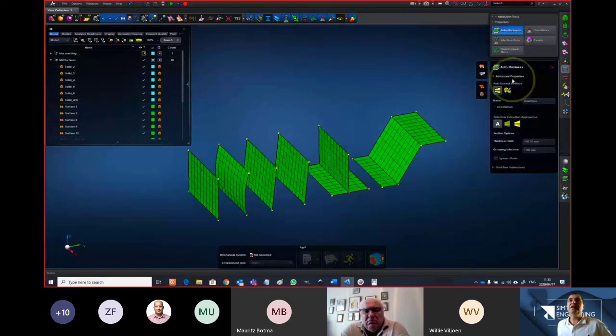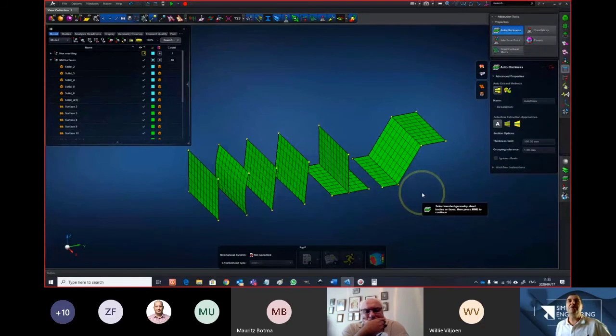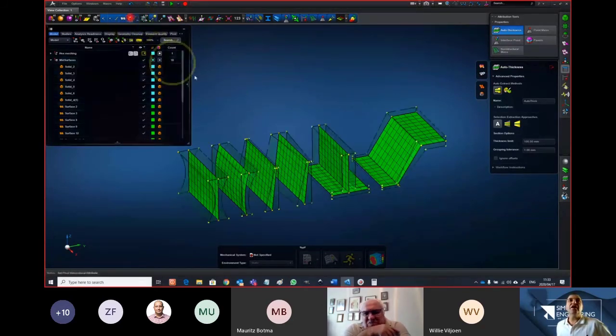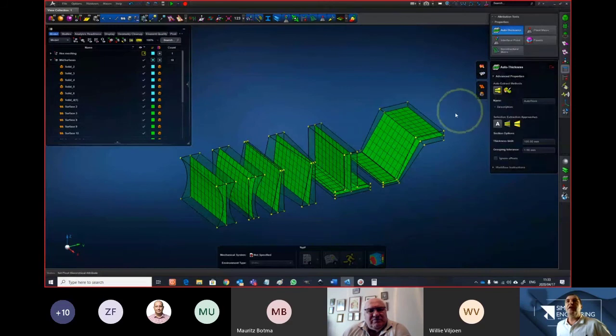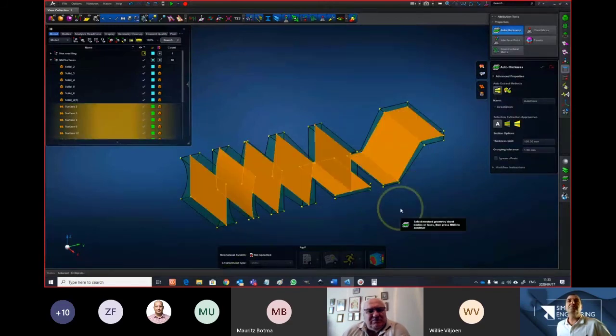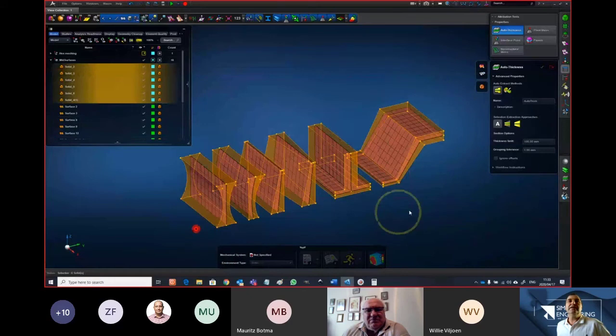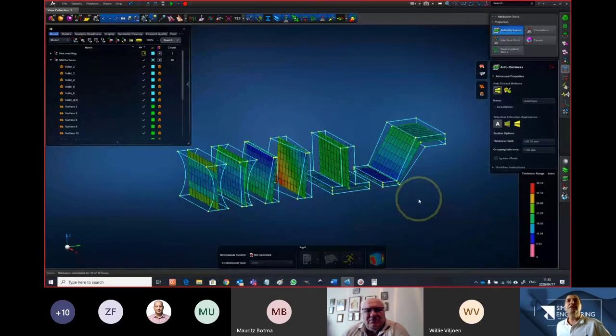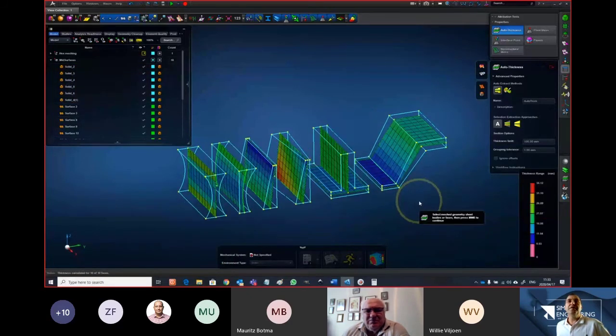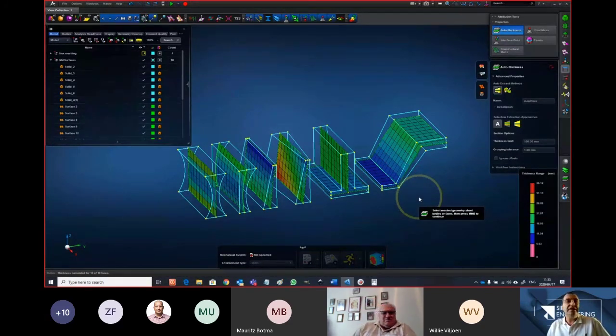requirement, is that you need a mesh, because the mesh actually dictates in many cases the outcome as well. So you have to have a mesh, and then of course you have to have your bodies. So it's now just a matter of selecting the mid surfaces, middle mouse click, selecting the bodies, and the thicknesses are automatically assigned. The important thing here is that the mid surfaces didn't need to be created in Apex using the mid surfacing tools.